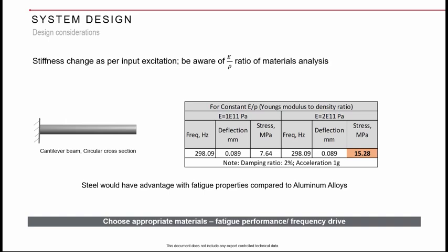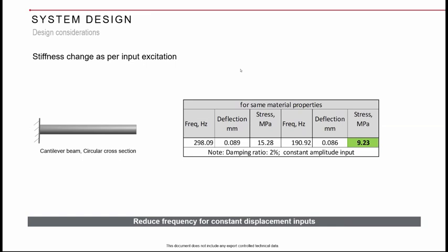But what advantage you will have when you change from aluminum to steel in certain cases is the fatigue properties. Fatigue properties of steel would be quite superior compared to aluminum, whereas aluminum may also need certain surface treatments, certain anodization, for protection against corrosion. All that will actually make aluminum inferior with respect to fatigue performance. So that way it may be helpful, but we cannot just say that changing from aluminum to steel will certainly help me every time. Sorry for the confusion here. I just inserted this part here. That was the thing which I was trying to bring.